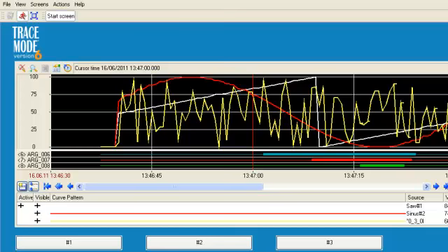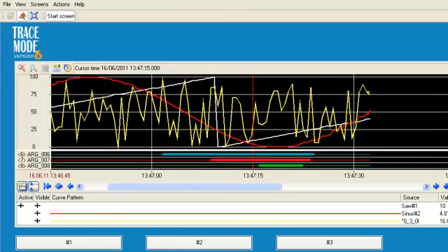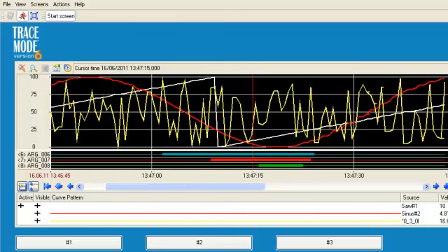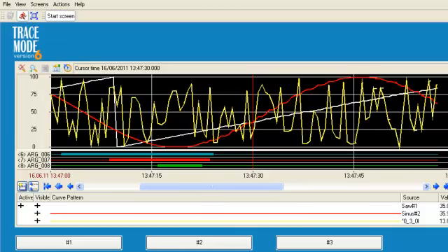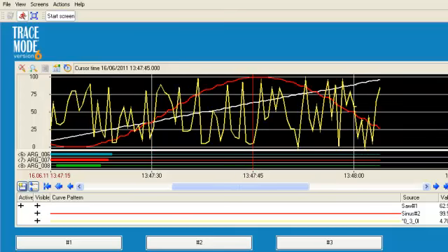Okay. We have developed a simple client-server system using Trace Mode Netlink Lite. Acting this way, we can easily add a new client PC to this system. We also draw your attention to one feature of Netlink Lite: smart connection to redundant standby Trace Mode servers. In case one of the standby servers fails, the console would automatically switch to the redundant node, independently tracing the active server without any additional tuning. Well, we finish our movie. Thanks for your attention and bye.